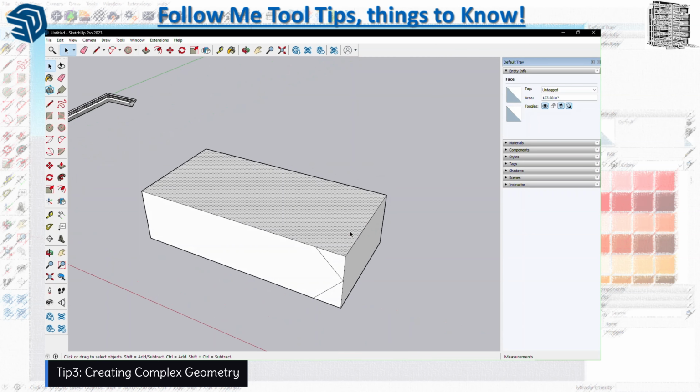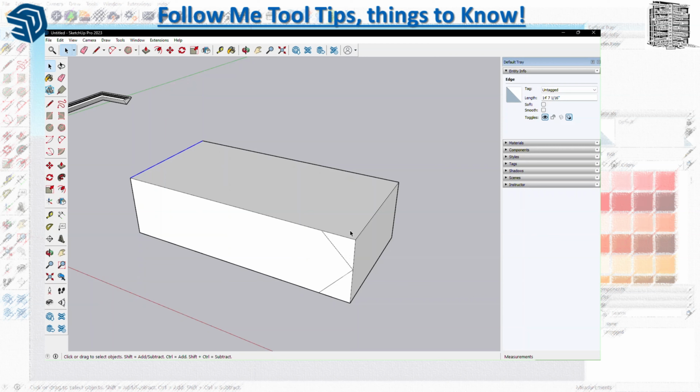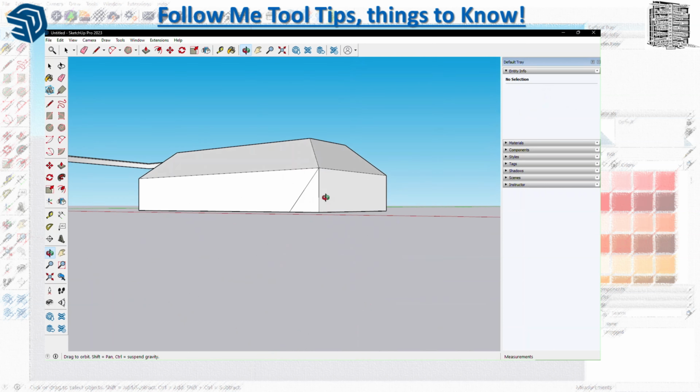Let's go to a different shape. Let's say we have a shape and then we want to create a different angle. You can select the lines, the edges of the shape, or you can select the surface, right? Let's first start with selecting the surface. I'm going to select the top, hit Follow Me, and say, let's follow this. With a quick click, it's going to create that shape.